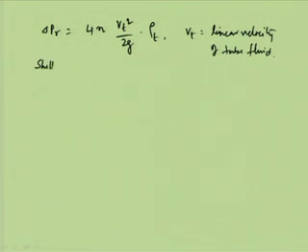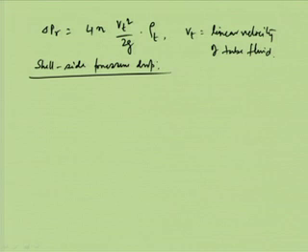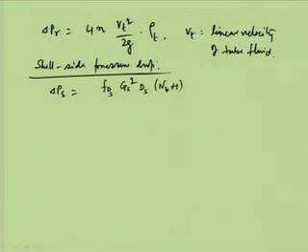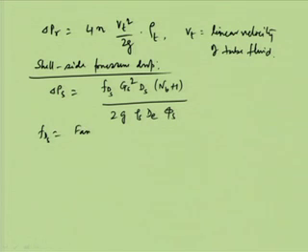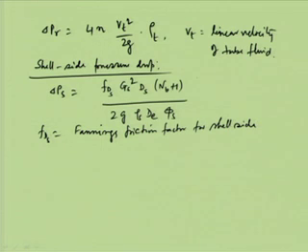Similarly, for shell side pressure drop, we have to calculate that delta P shell side is given as again Fd into Gs square, shell side mass flux, into Ds into Nb plus 1, divided by twice g rho S dE into phi S. Again the same thing, Fd S is the Fanning's friction factor for shell side. Most are shell side terms, so I am not repeating them.